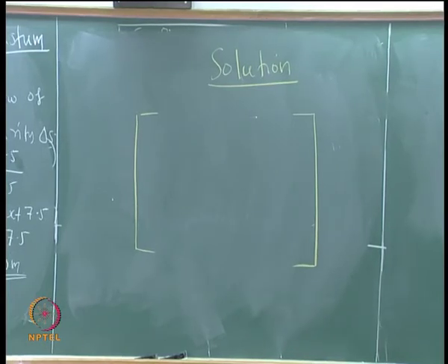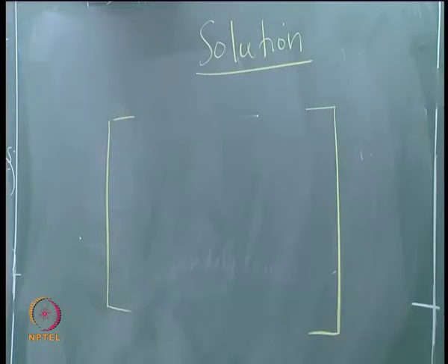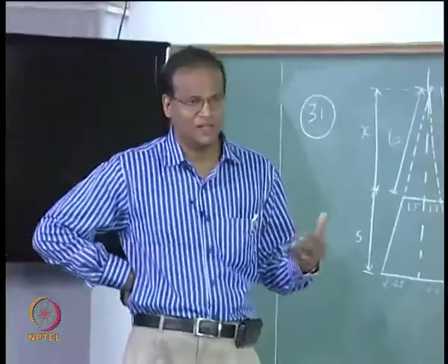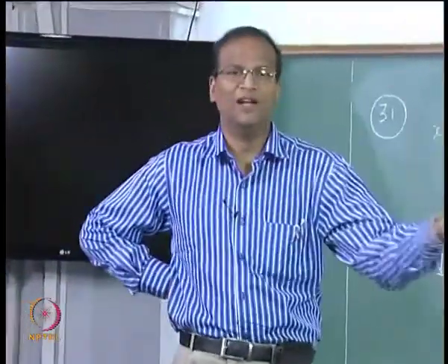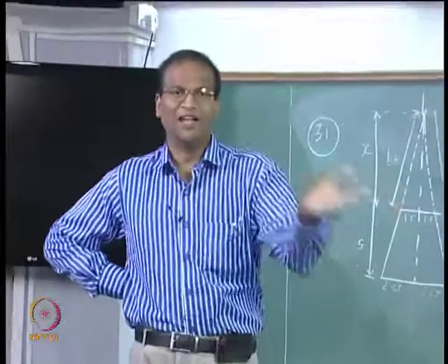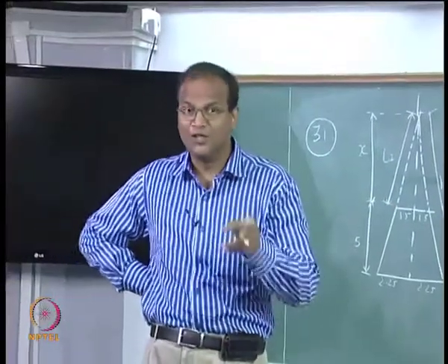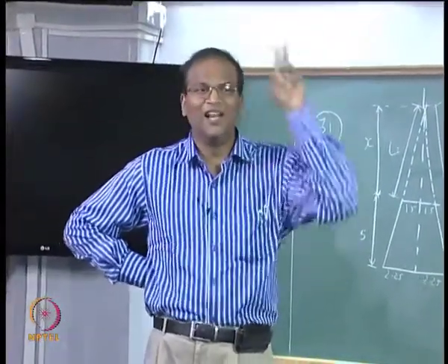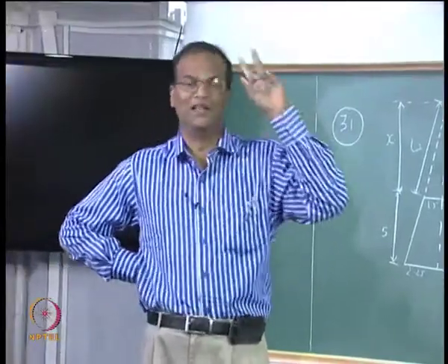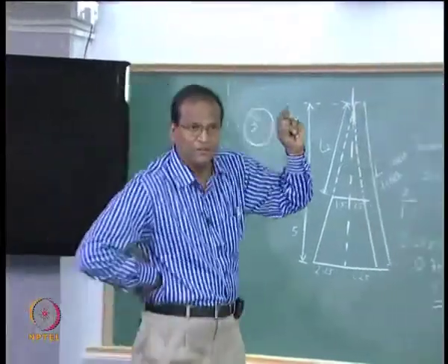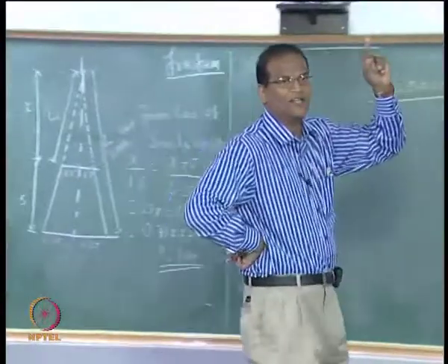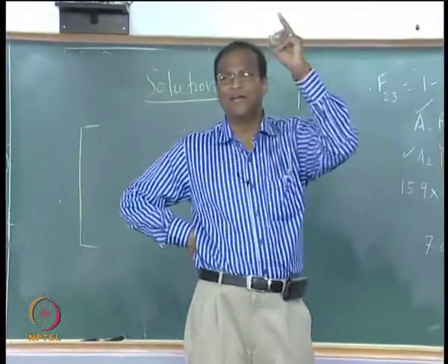However, if the surface is also changing, the dimensions are changing, which can happen with an ablating surface, such as a re-entry vehicle entering the Earth's atmosphere where a few millimeters of the surface evaporate and sublimate away, then the geometry will change. So geometry-linked view factor calculations will be there, that is the state of the art if you want to do radiation calculation at a level which will make it journal worthy.